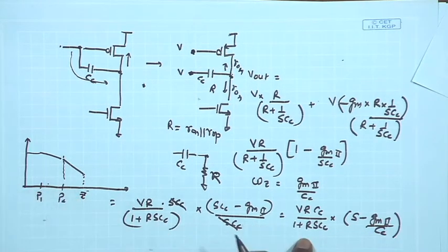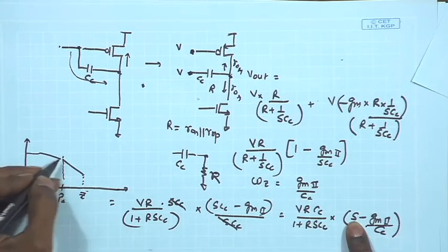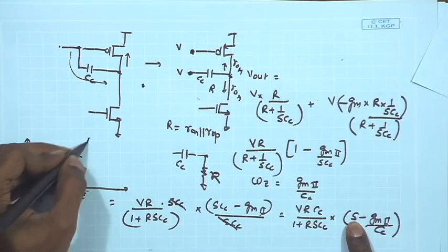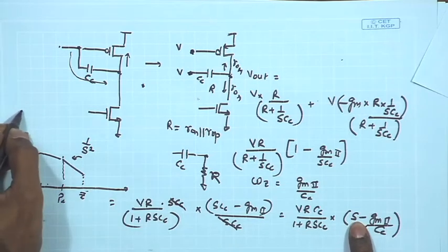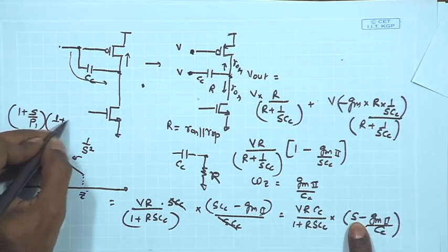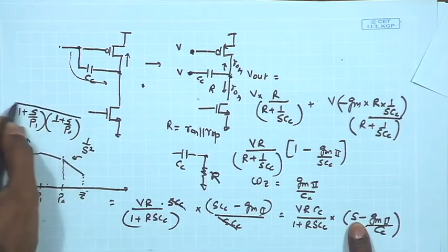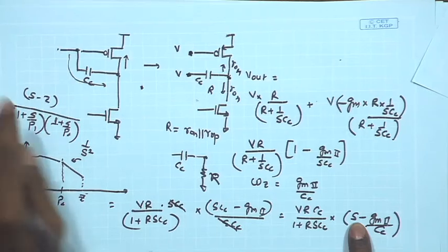And after this we can say that once you cross this 0, this omega term becomes dominant, you can ignore the second term. As a result, this is going to cancel out with the other two terms that you get till this point. So, till this point the expression of the overall gain was dependent upon omega square, but after the 0 you get another omega in the numerator, right, because of the two poles. Remember, you have 1 plus S upon P1, 1 plus S upon P2 in the denominator, and now you are having the S minus Z term coming over here.